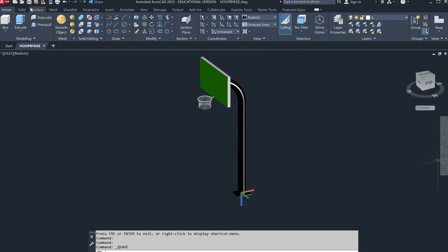I suggest you save it and then insert it into your Revit gymnasium as a DWG. When you save this, it saves as a DWG. Make sure that you know where you save it in OneDrive, and make sure that your names are correct and everything. And then when you insert it, all the properties are going to come together, but you need to insert two of them, or at least make a copy when inserted and rotated. They're going to be against it.